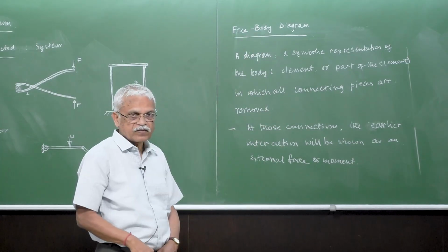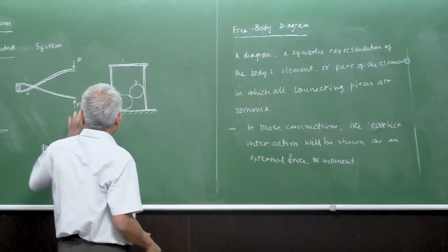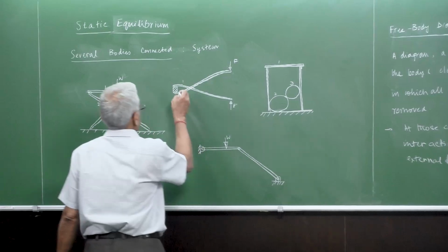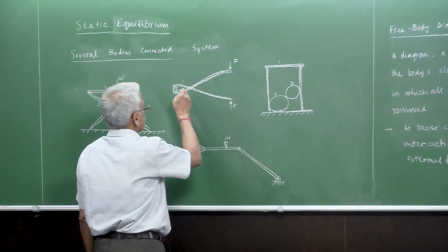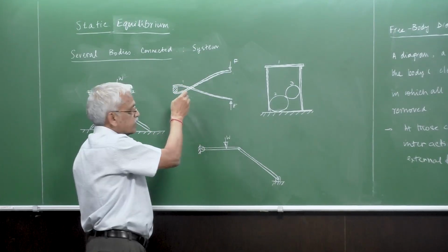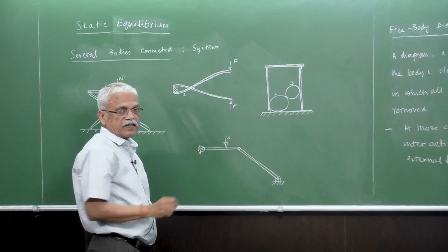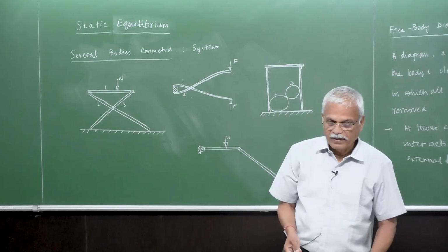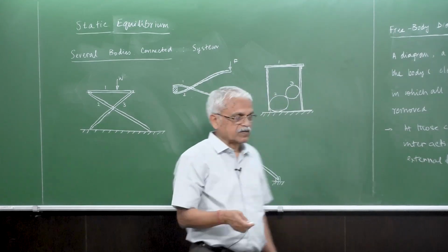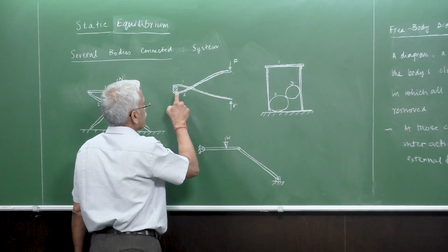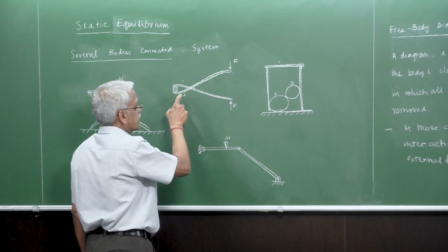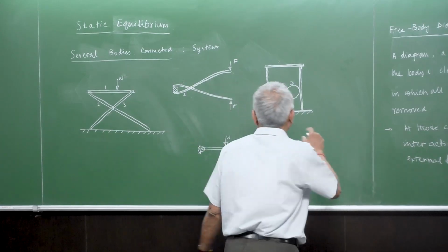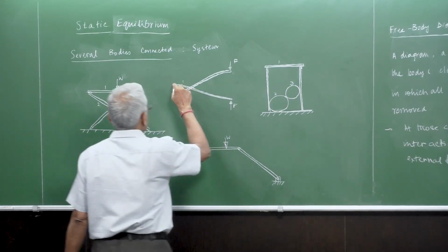This is a very important part of our analysis. We can take out any part of this, whatever is of interest. Here, for example, in this pliers, we can isolate the cylinder and show it as an independent isolated body with all the connections removed. That means the top handle and bottom handle have been removed, and the earlier interactions, meaning this was holding this one.